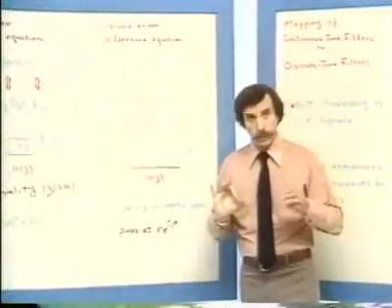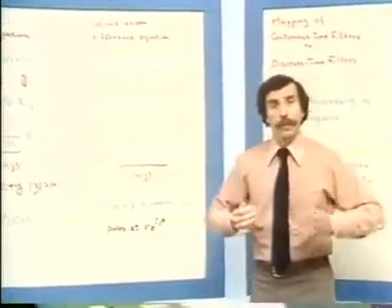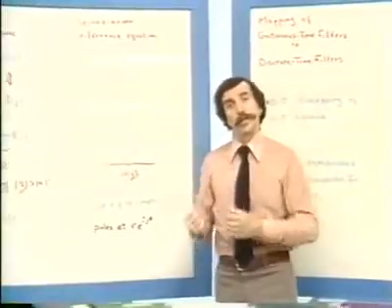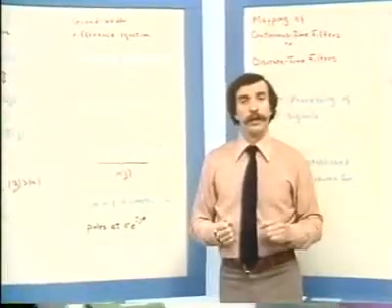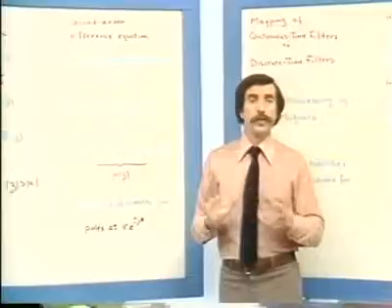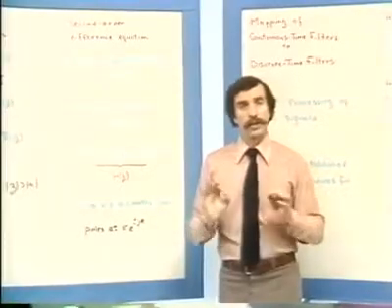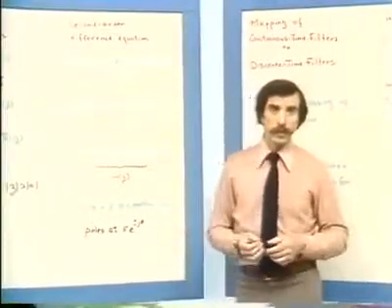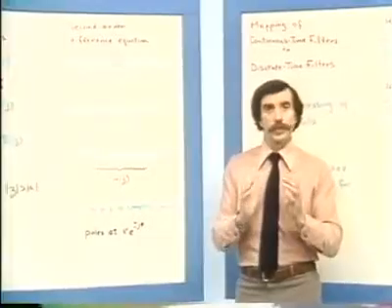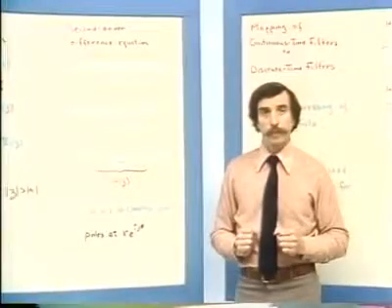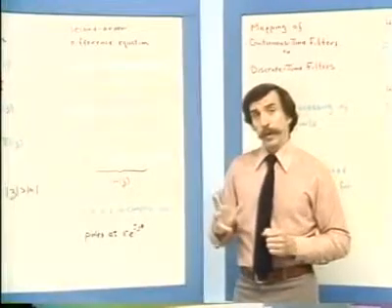Again, there's the question of what we assume about the region of convergence. I haven't specified that yet, but if we assume that the system is causal, which I will tend to do, then that means that the region of convergence is outside the outermost pole. Now, where are the poles?